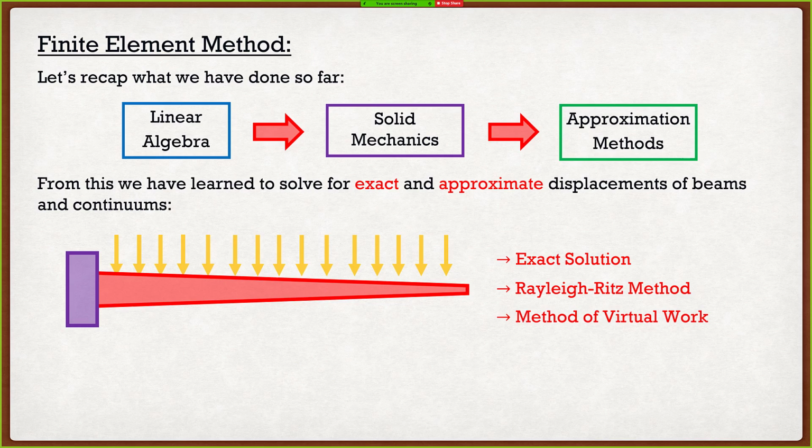If I wanted to solve this beam, we know that it has a variable moment of inertia because, of course, that cross-section is decreasing. So can we use this equation? If I were to just find I as a function of x1, could I not just substitute that function into this equation and be good to go? What do you guys think? If I could capture I as a function of x1, could I not just substitute it in and say we're good to go? All right, I'm hearing a lot of yeses.